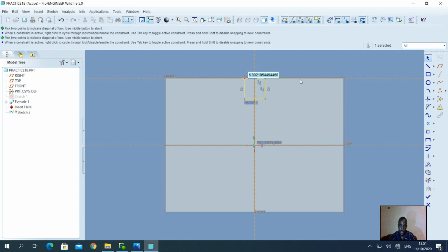You can also dimension a component by double clicking the part. Though at first, when you start to make this thing from scratch, like what we did previously in creating the rectangle, this outer rectangle, we had to select everything and then we had to use this modifying tool right there. Once you have got that, the other features that you'll be dimensioning, you can double click the dimension itself to put the value, because they'll be drawn in proportion to what you have previously drawn. So I can double click this part and then I can select this side as 10.